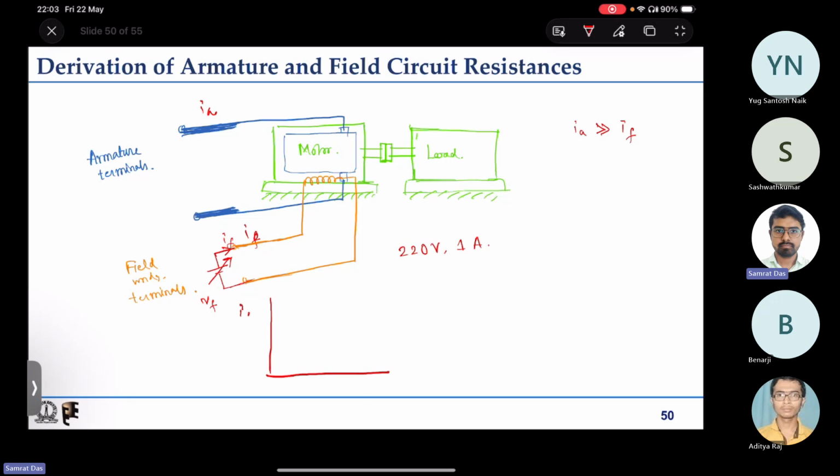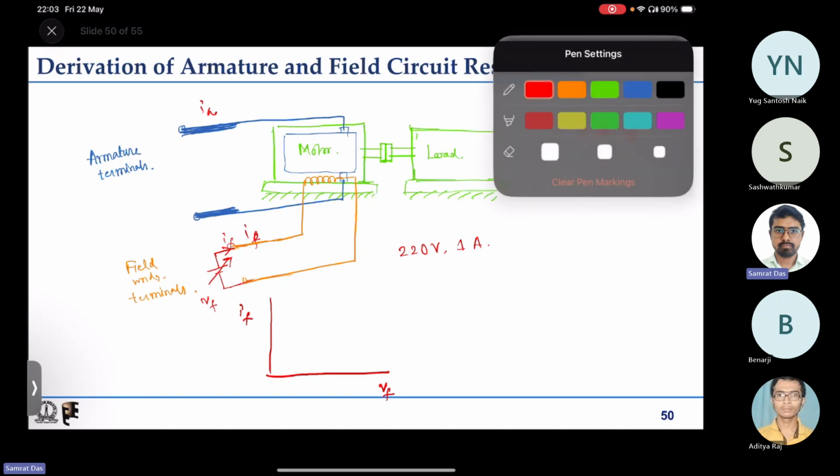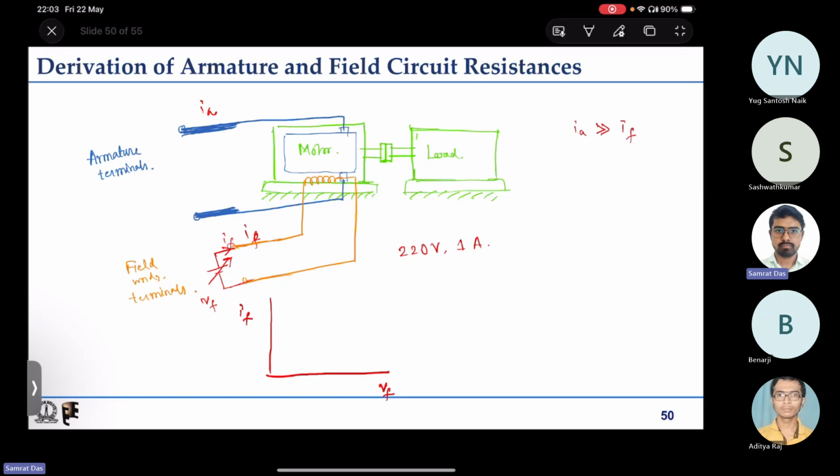Say you have the If, the one which you are measuring, and you have the voltage which you are setting to make that much amount of current flow. So say you start with 1 ampere, you make 1 ampere current flow for some time by applying some voltage. Some voltage is required for 1 ampere, say, that much you have passed. So you get the first point.